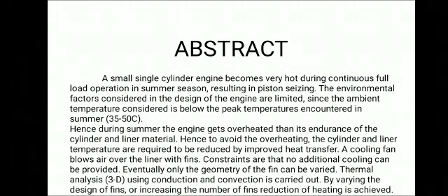A cooling fan blows over the liner with fins. Constraints are that no additional cooling can be provided. Eventually, only the geometry of the fin can be varied. Thermal analysis using conduction and convection is carried out. Increasing the number of fins reduces heating.